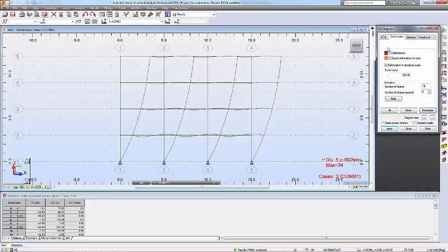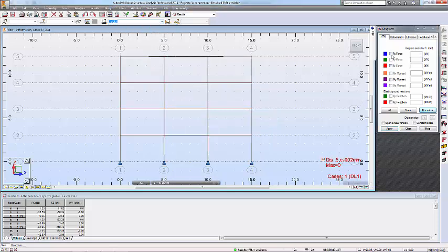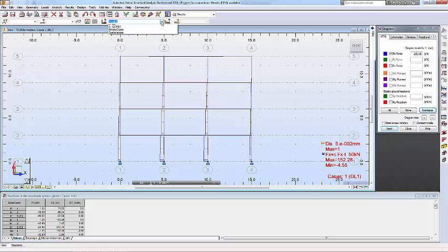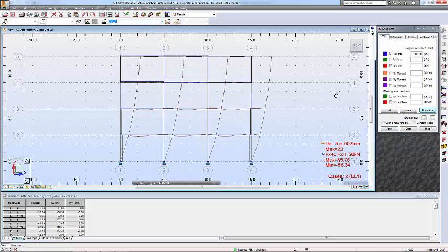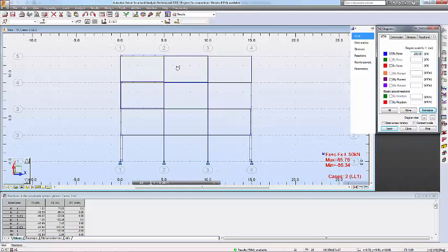After deformation, let's have a look at the member force, the actual force for the dead load. So click on actual force and click on this one. So that's the actual force. The actual force accumulates layer by layer down to the ground, so it increases gradually from top to bottom. And live load. So this is live load. I need to maybe disable the deformation and click on apply, so only the actual force will display here.